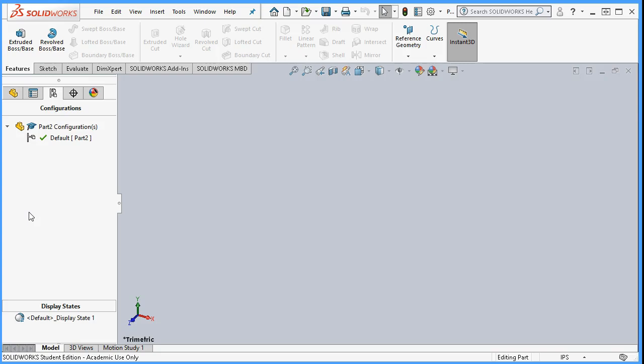Anyway, somewhere in that grouping. And then lengths from 1/8 of an inch up to 4 inches. Rather than having what would amount to 1,000 different files, I could put in groups and have the configurations drive the physical features so that I have one socket head cap screw file with potentially hundreds if not thousands of parts.